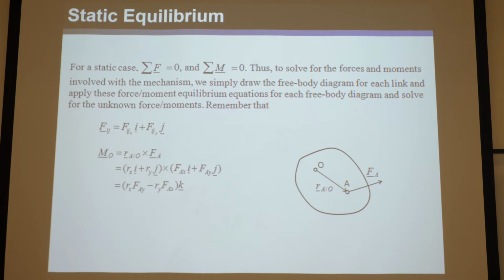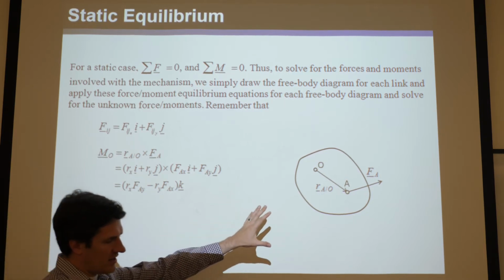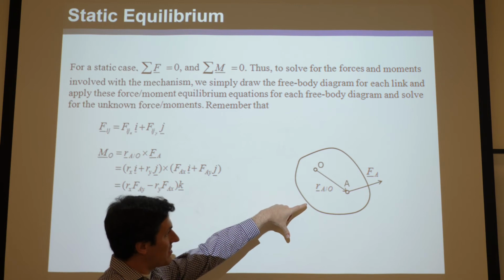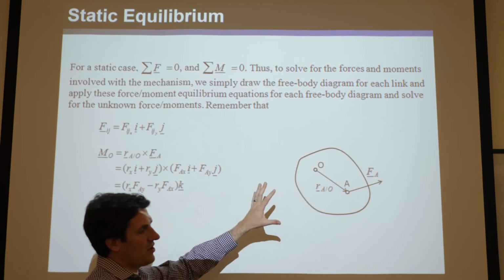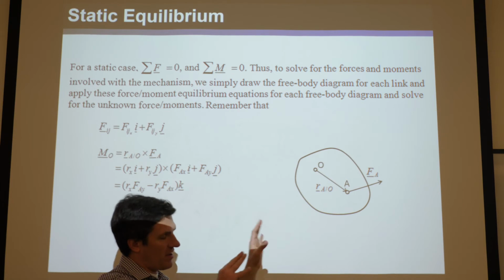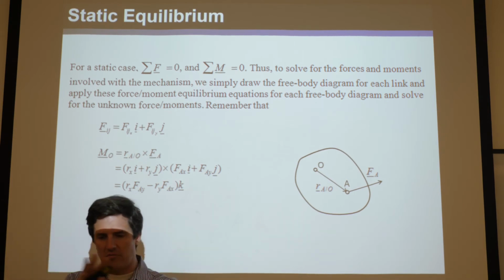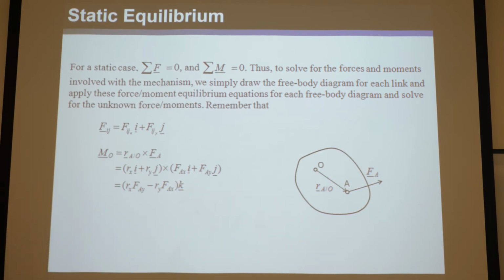So if you had a bunch of forces acting on some potato here, and they had their lengths according to their magnitudes and their directions established, you could think about all their points where they're loading it changing. You could shuffle them around any way you want, because those forces have no knowledge about their location embedded in the math. And all you do is you sum their x components and have them equal 0, and you sum all their y components and have them equal 0. And notice those equations, when you do that, are independent of where the force is being applied.